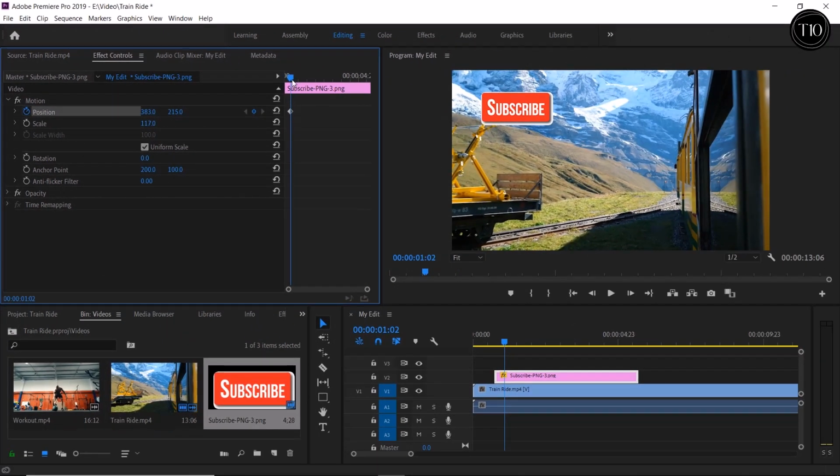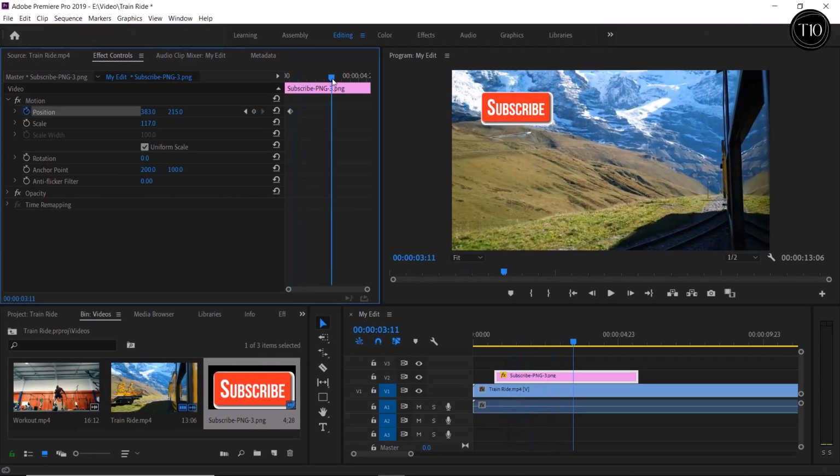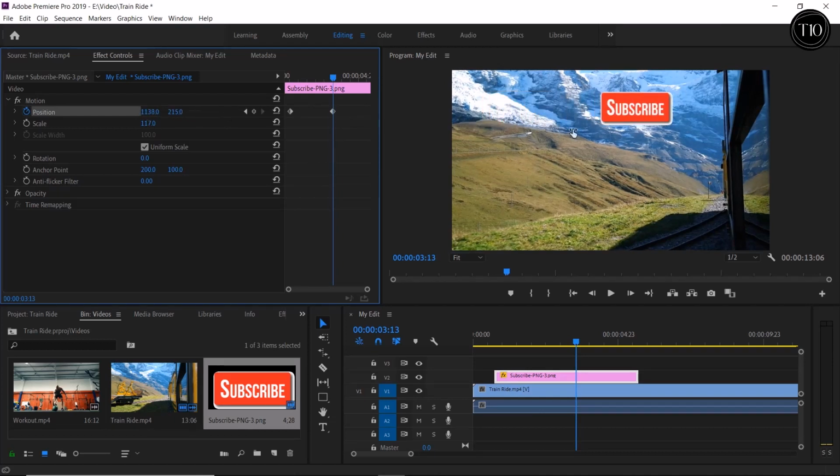Now let's move a little bit forward. Like this. Now we are going to change that position. Let's change the value from here to the right side. Now you can see Premiere Pro automatically created a second keyframe as it saw the change in the value. So we have point A, the beginning position, and point B, the ending position. Two points with a different value. Let's see what happens when we play the clip.